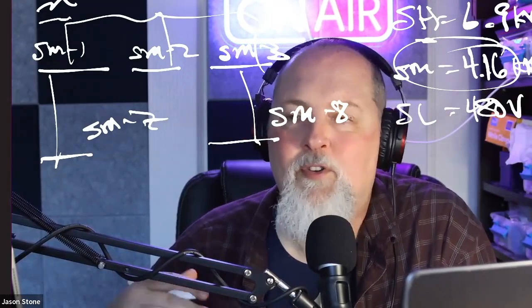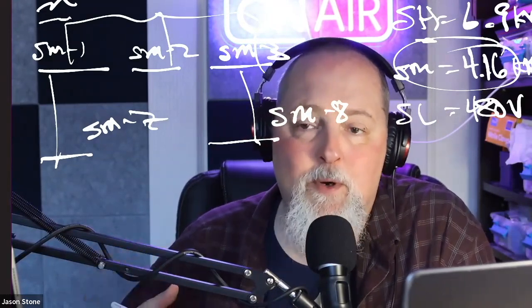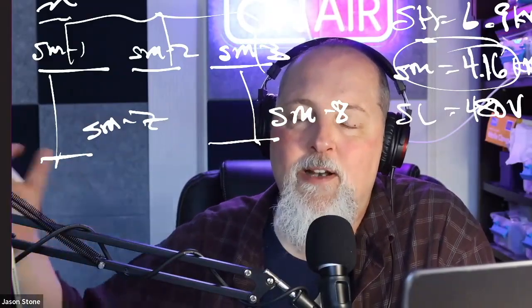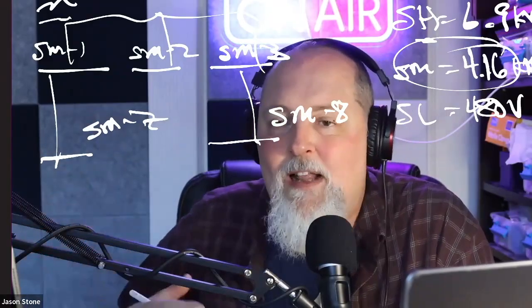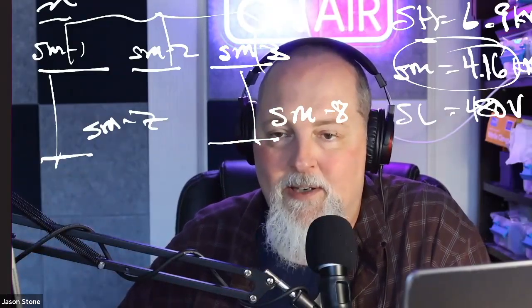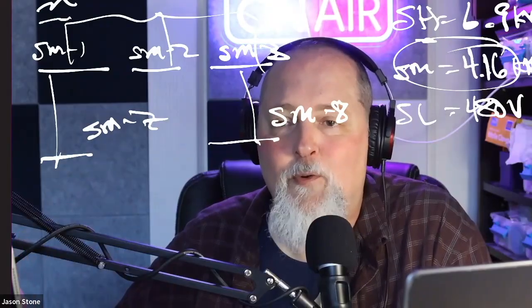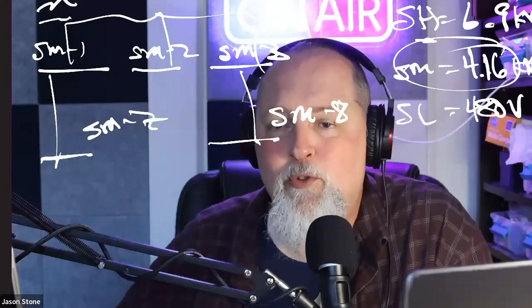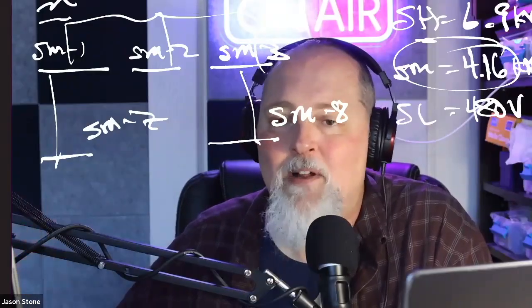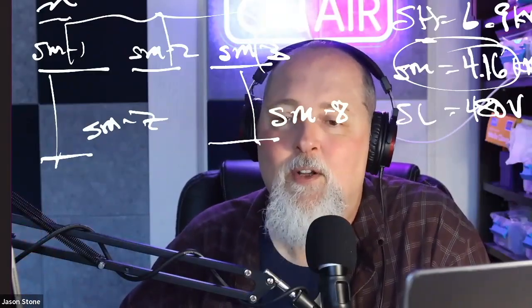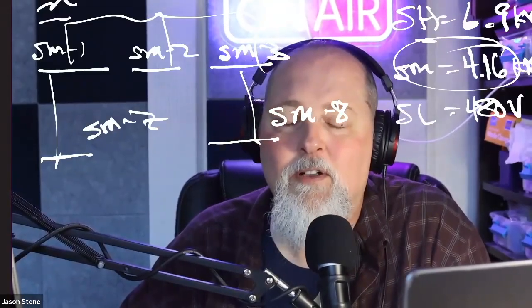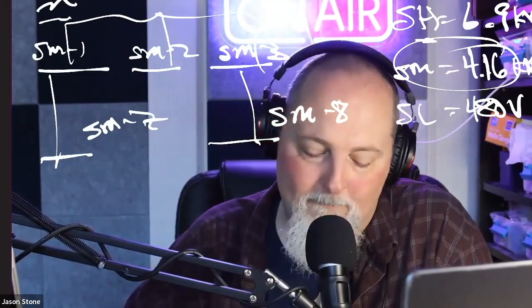If we had a reactor scram, which means we're no longer making electricity, and we lose our connection with the grid, we still have to be able to operate pumps and provide cooling to the reactor. Because if you think of Fukushima, if you lose the ability to cool, bad things happen. The core melts down, it melts out the bottom of the reactor vessel. We don't want that to happen. And so these two buses are very, very critical to preventing that from happening.